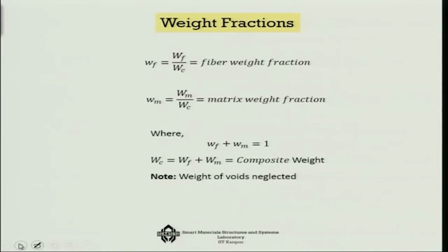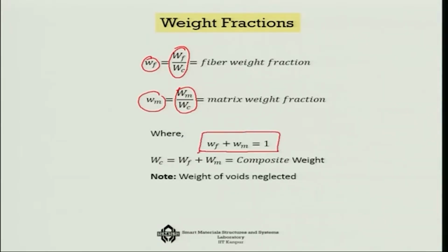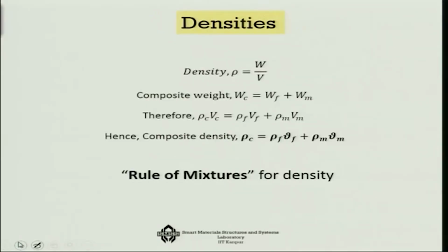Now if you look at the weight fraction, that is actually Wf over Wc, and Wm over Wc. Now void has no weight, which means that for weight fraction, Wf plus Wm equals unity, unlike the volume, where the volume of the voids you have to consider.